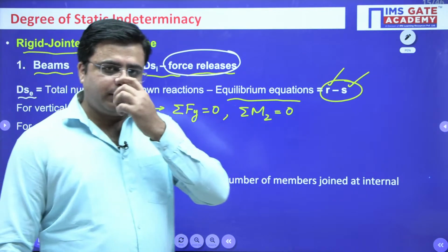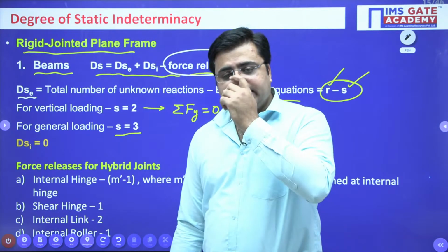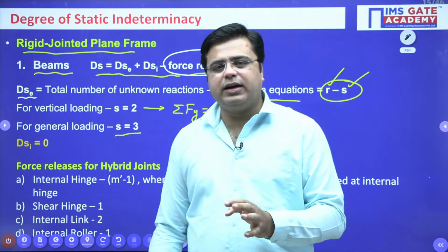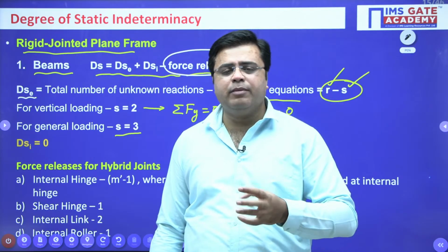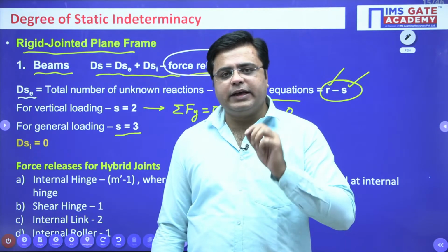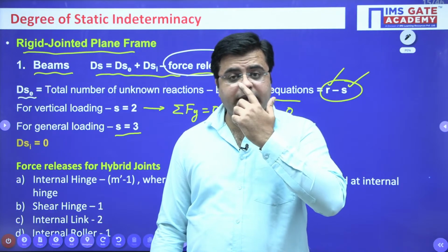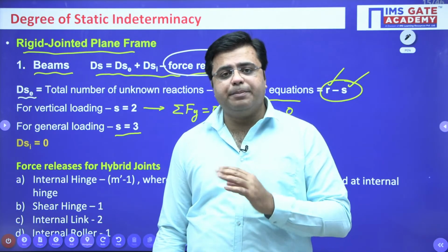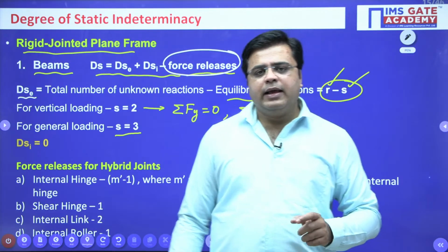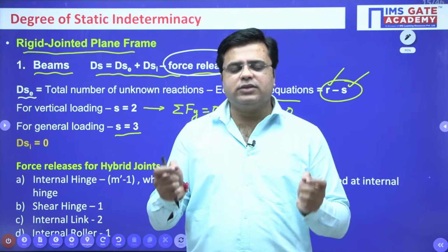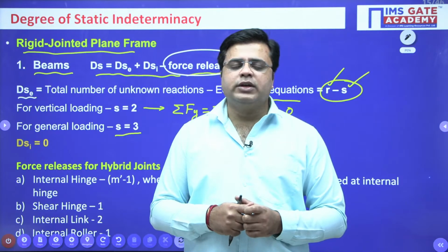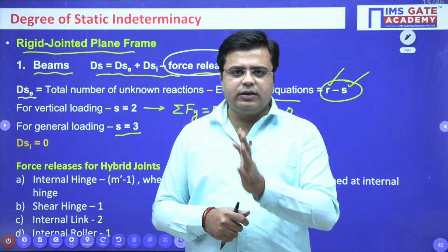Okay. If we know the external reactions, it doesn't matter whether a beam is a determinate beam or an indeterminate beam, right? If you anyhow calculate the external reactions, then it is very easy to calculate the shear force and bending moment at any section in the internal structure of the beam, right? If you know these support reactions, then you can easily calculate the value of shear force and bending moment at any section present in the beam.